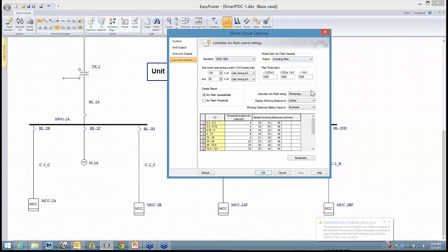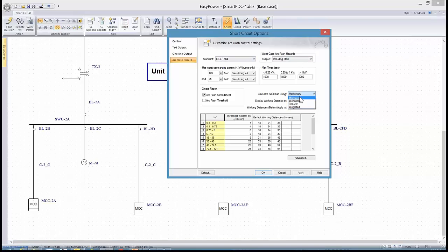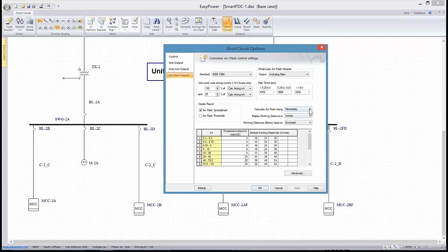In this particular control setting, usually momentary is the worst case, and so that'll give you the longest spike, the highest spike. But in terms of certain kinds of faults, based upon where they are in the system and how much impedance there is and what the trip settings of the breaker, the protective devices are, interrupting in 30 cycle may be part of the equation.